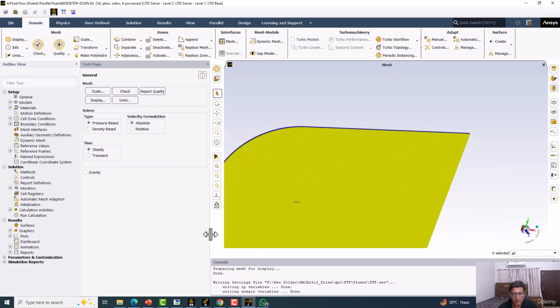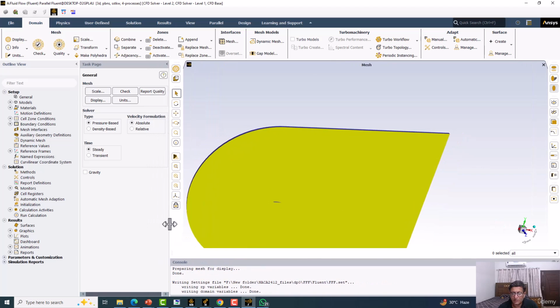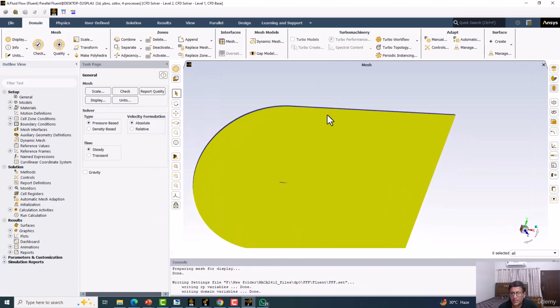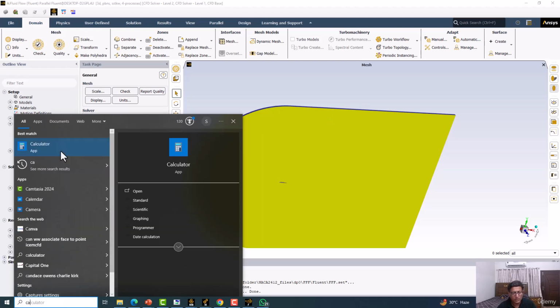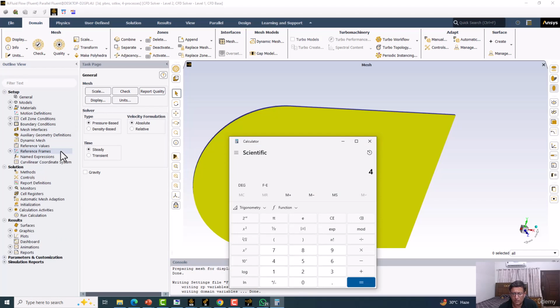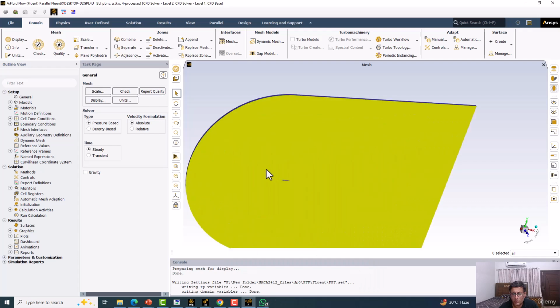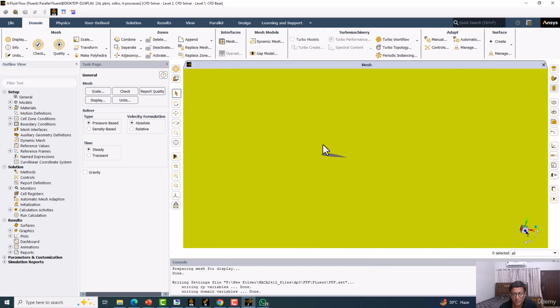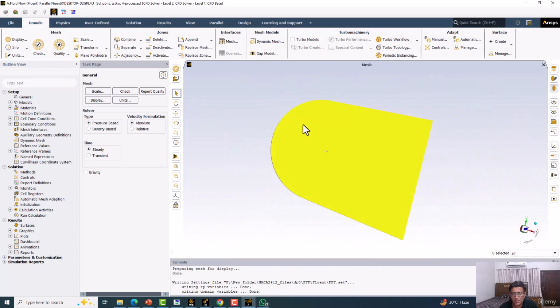Then this is going to be the pressure-based solver because the Mach number is less than 0.3. Velocity right now we have is 43.8, and the speed of sound at sea level is 340, so it's less than 0.3, and I don't expect this to be a compressible fluid. So even you can try to reduce this value to the lower side also, but 43 is okay.